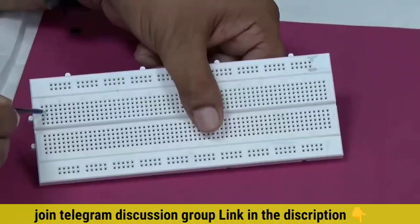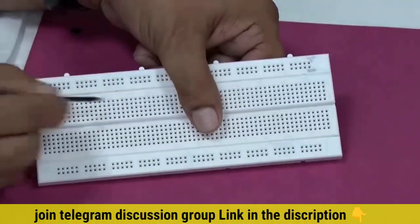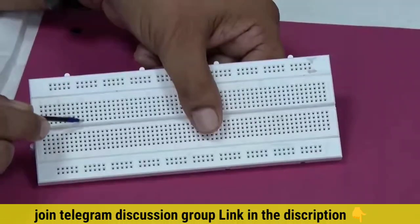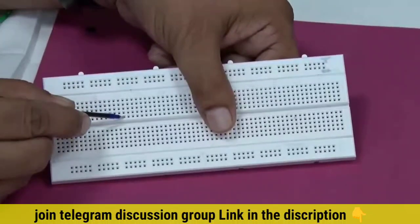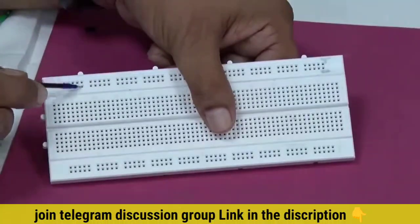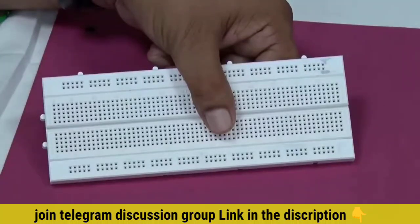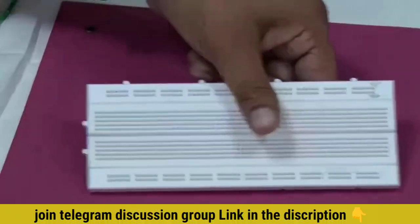Similarly for each of these lines which are along the width of this rectangle, these 5 are internally connected, these 5 are internally connected, these 5 are internally connected, but one line and any other line are not internally connected. Similarly here, this one line and this other line are not internally connected with each other. So keep this in mind when we build the circuit.